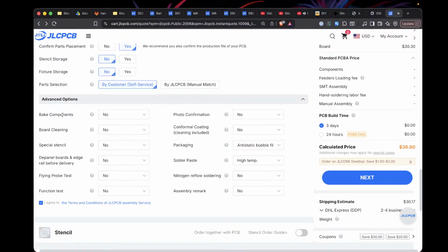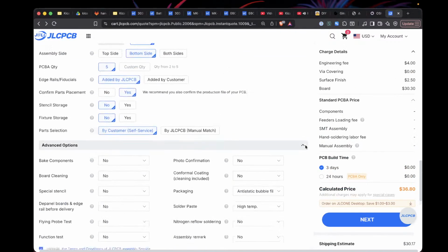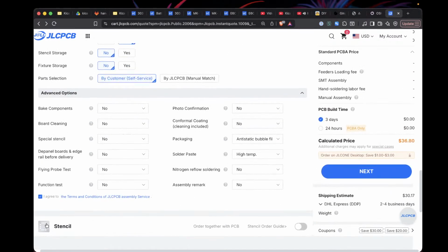When I worked at a synthesizer company, we did have a whole bunch of failed boards because the LEDs were in a humid environment, and then they sent it through the reflow oven without baking it first, and there were all these failures. It was a huge batch of boards that all had problems, and we discovered it was because they didn't bake their LEDs. They were sitting in a humid environment. That was 4MS, a Eurorack modular synthesizer company. They're still around. They make really great products.